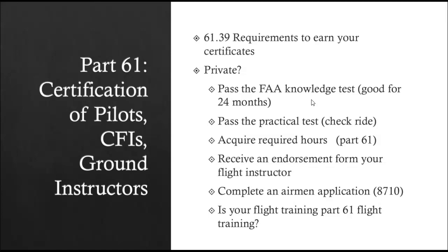It's important for you to determine whether your flight training was conducted under Part 61 or another part, for example Part 141, because that will dictate some of the requirements to be qualified for the check ride. MTSU's flight school is a Part 141 flight school. Because of that, the minimum number of hours to be qualified for the private pilot check ride is reduced from 40 hours under Part 61 to 35 hours under Part 141.